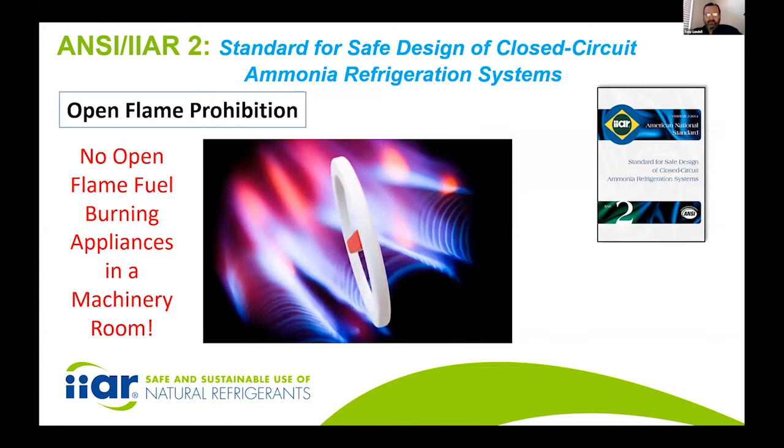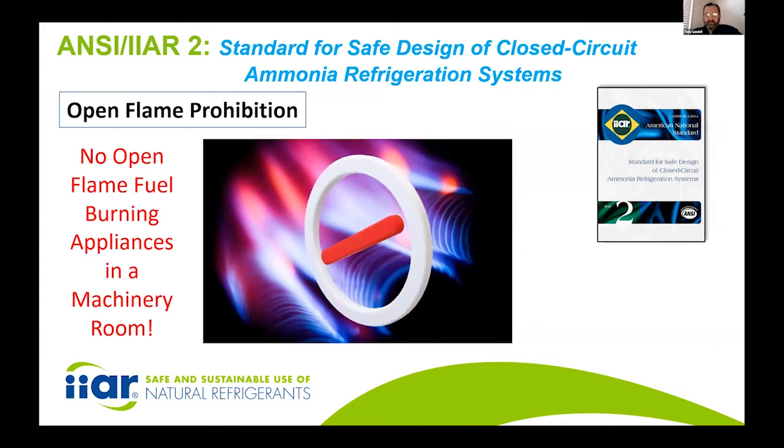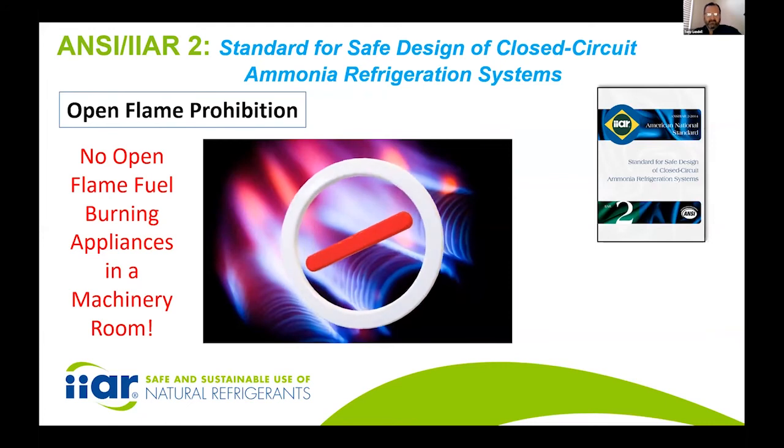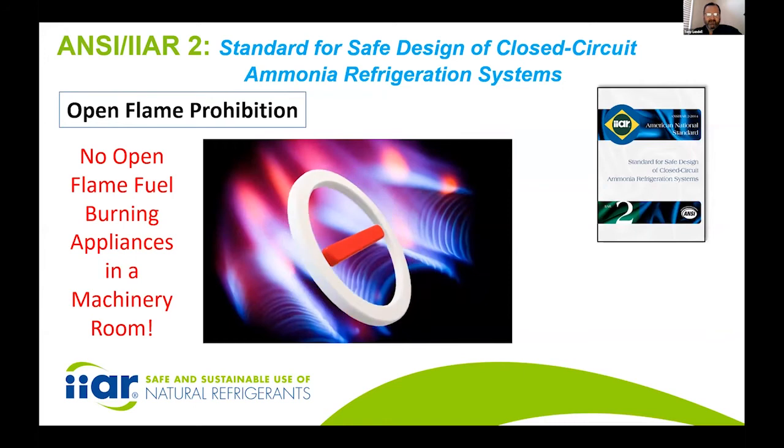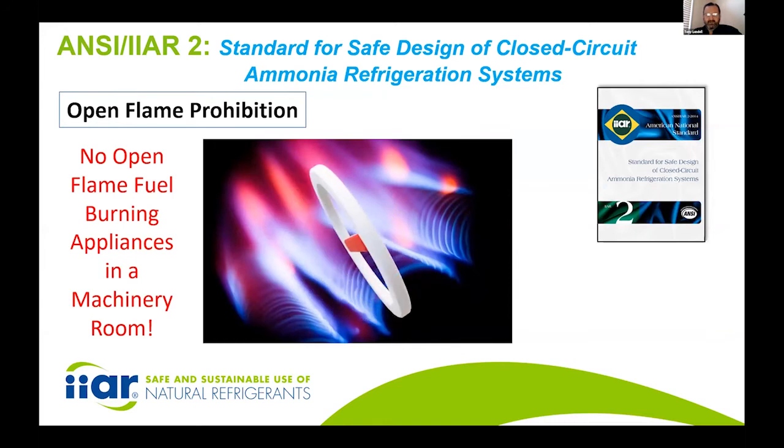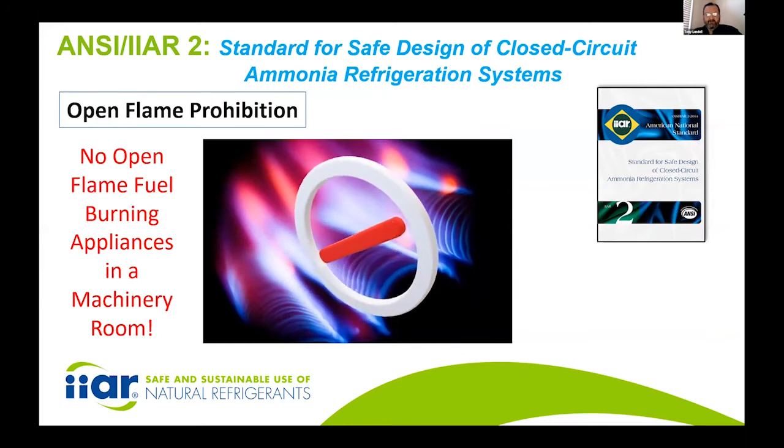One item that is a prohibition is having an open flame. So there should be no open flame or fuel burning appliances in a machine room. That's just one item that you do want to avoid, because you never want to have a chance that if there was an ammonia release, it could ignite the ammonia vapors.